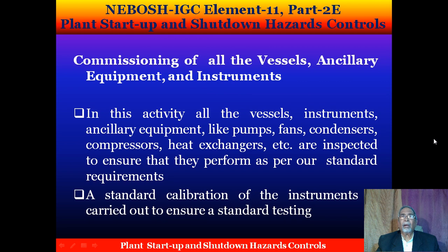Commissioning of all the vessels, ancillary equipment and instruments. In this activity, all the vessels, instruments, and ancillary equipment like pumps, fans, condensers, compressors, heat exchangers, etc. are inspected to ensure that they perform as per our standard requirements. A standard calibration of the instruments is carried out to ensure standard testing.